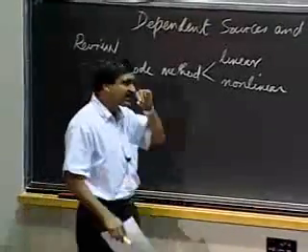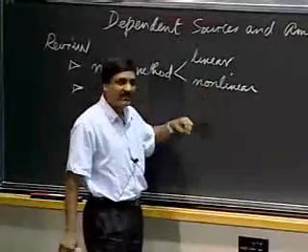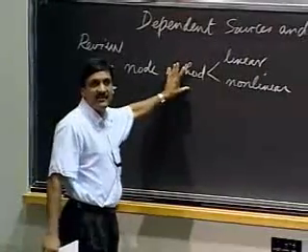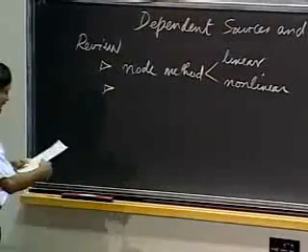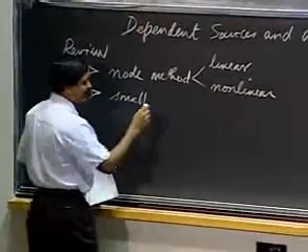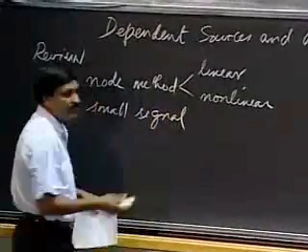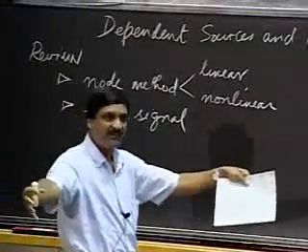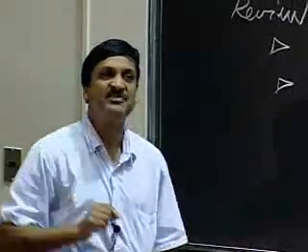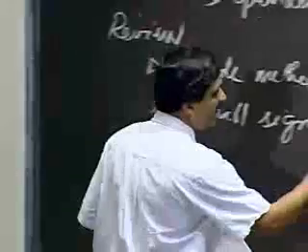So the last week was focused on nonlinear circuits, and we spent the first lecture talking about a straightforward application of the node method, which gave us a bunch of nonlinear equations that we had to solve. In the last lecture, we talked about the small signal trick. What we said is, if you look at the whole space of nonlinear circuits, then within that space, if we focus on small variations, small perturbations about the operating point, then even the behavior of nonlinear circuits in that small regime would be linear. So small signal method.